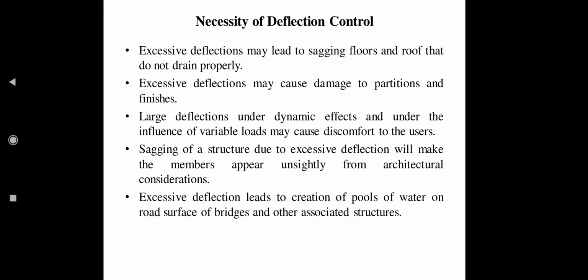ceiling and other things. Large deflections under dynamic effect and under the influence of variable loads may cause discomfort to the users. So if we are sitting on the first floor or a second floor and the floor we are sitting on has a large deflection, then we will experience discomfort while moving on that floor. Hence, it is necessary to control the deflection.